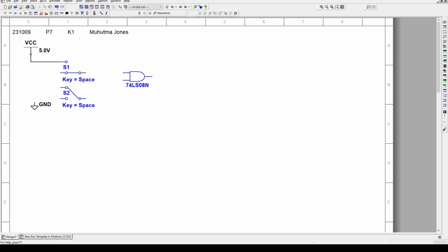And I didn't have to click or anything. I just turned the corner at that point. And I'm going to click. And now I've got VCC from power going into the first throw of this switch. The bottom switch, I want to hook that up also to power. The top connection, I'm doing the same thing. Coming over here, turning the corner, and hooking up to the original elbow there because that's probably the closest place that I can access power.